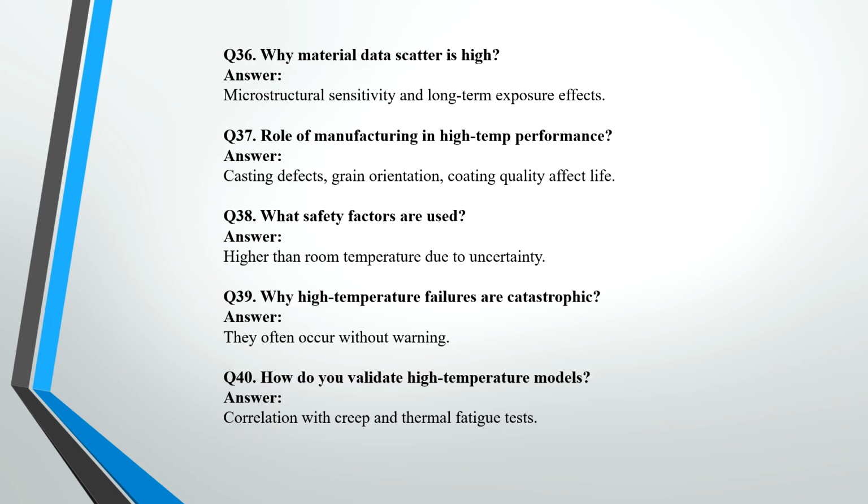Why is material data scatter high? It's due to the microstructure sensitivity and long-term exposure effect. What is the role of manufacturing in high temperature performance? Casting defects, grain orientation, and coating quality affect the life. And the next question is, what safety factors are used? Higher than room temperature, due to uncertainty.